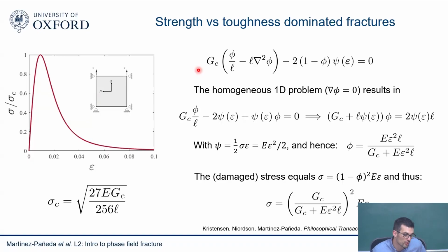You will also have some sort of strength measurements of steel or glass. What sigma c is in steel is a topic of high debate, because in brittle materials it's very simple to know the strength. In ductile materials you will ask, is this the ultimate tensile strength? Is this the local fracture stress that you will get because of triaxiality and different stress states? I'll discuss that a bit later on. But in principle, let's say you know the strength of your material. Since you know Gc, Young's modulus and strength, you solve for your L. That's the idea.